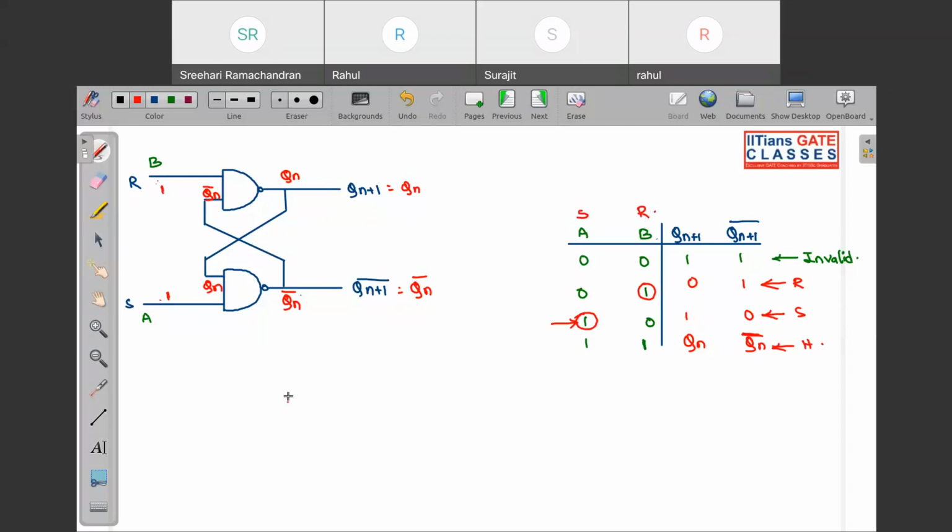So always remember, even in NAND latch, your set input is directly opposite to Qn plus 1 complement. But in old textbooks, I am telling you this repeatedly, for NAND gate you will find set bar opposite to Qn plus 1, because in NAND gate 0 has more priority, and 0 we usually describe with a complemented term.